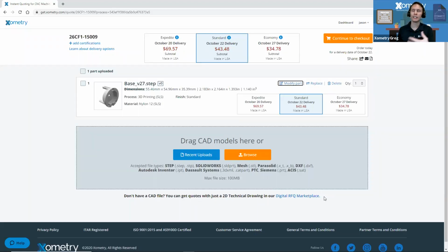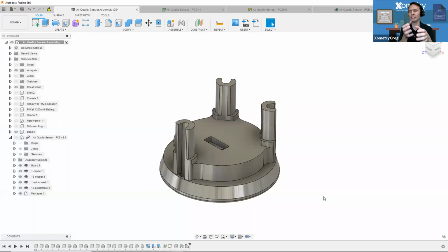Yeah, and something that's kind of unique about SLS is printing in a thermoplastic, right? It's printing in nylon. Something I've been accustomed to doing in a prototype process, especially if I know that I'm tweaking my design in CAD, is I may take that design, print it out in SLS, and if I'm finding interference or fit issues, this nylon is enough that you can drill into it, you can hack it, you can modify it, and then reflect some of that physical manipulation in your CAD, so offsets and holes and other features. So I like it as a prototyping tool, because unlike some other materials that may be more brittle, SLS is pretty durable even from a hacker standpoint. You could really modify the part to fit your needs in a prototype situation.